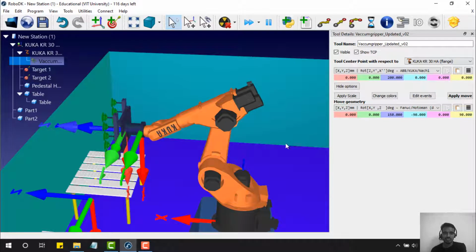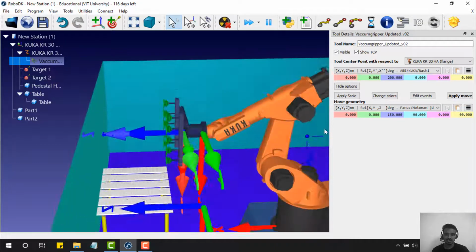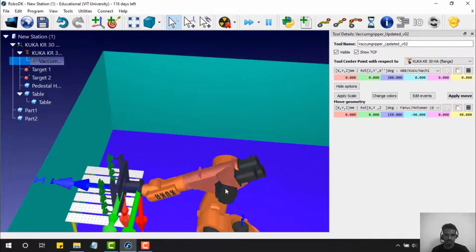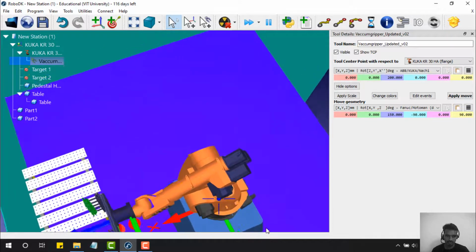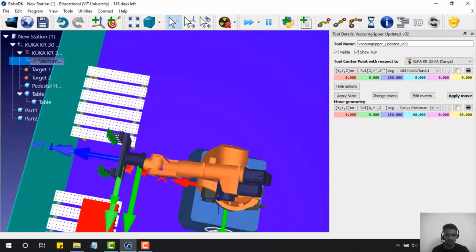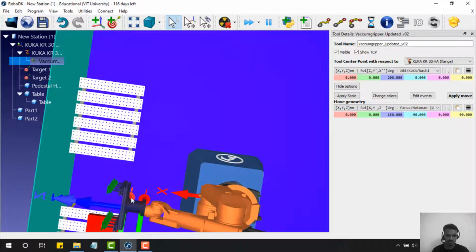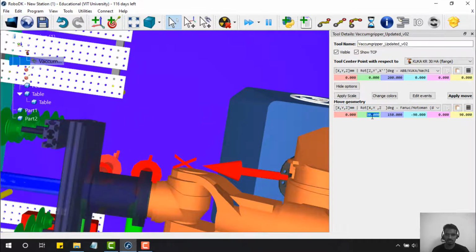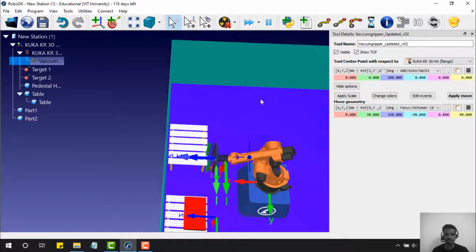What I was doing was clicking on any of these, readjusting the geometry by pressing here, and changing the scroller, so we can understand exactly how we can move. And you can also see and identify by left clicking and zoom in, zoom out. So you can see there is a small orientation issue here, so we can fix it by moving it along the Y direction. I think it looks fine.